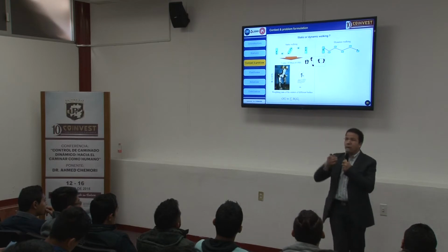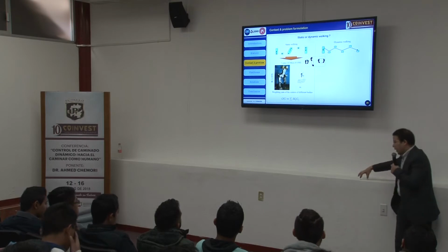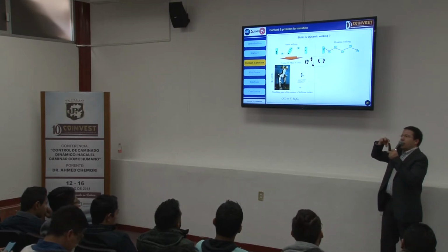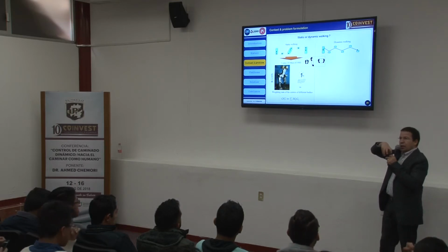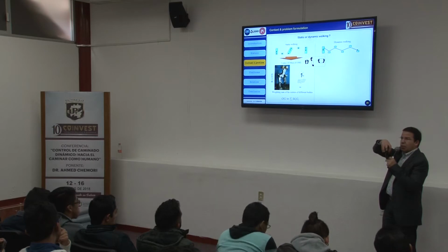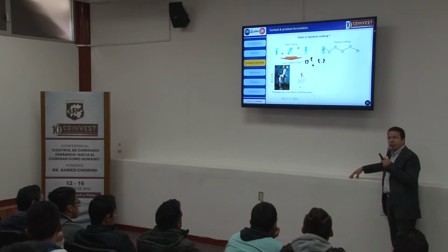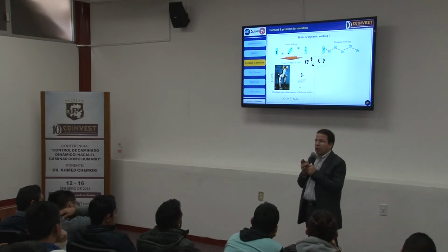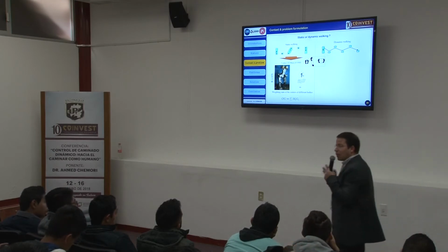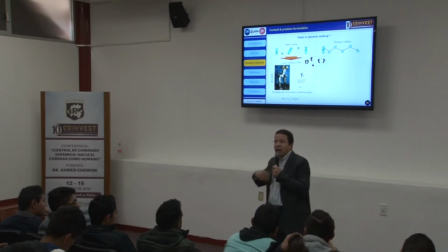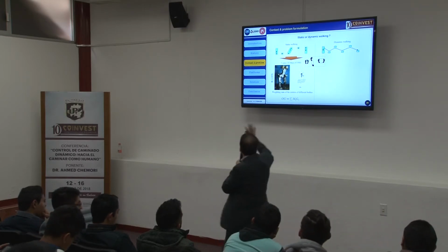Now, this is the static walking. In the case of a robot with many legs, you have just to construct the polygon of support, the polygon relating the points of contact with the ground, and you have to ensure that the center of gravity or center of mass, its projection, is still all the time inside. So if you move one leg like that, the projection is still inside and the robot is still stable. It's very easy to do this kind of walking, but the problem is that you cannot do a high-speed walking or dynamic walking because it's static. You have to do something like that, like that, like that. This is the static walk.